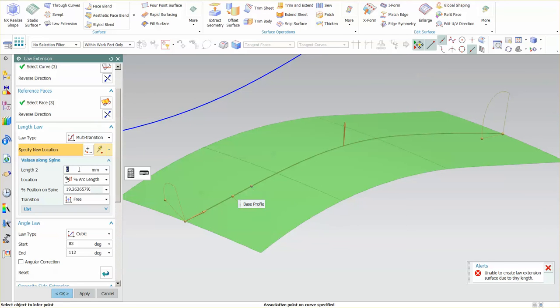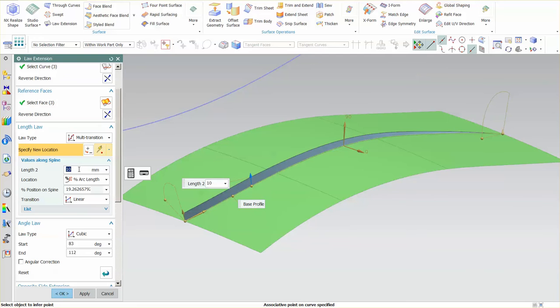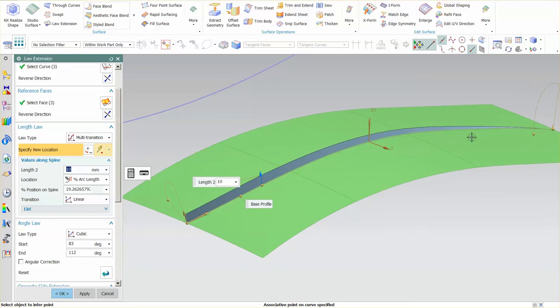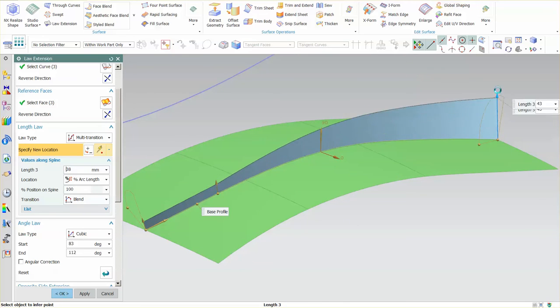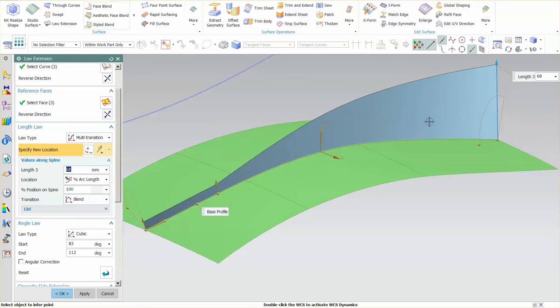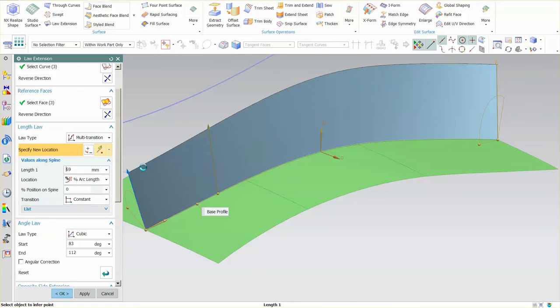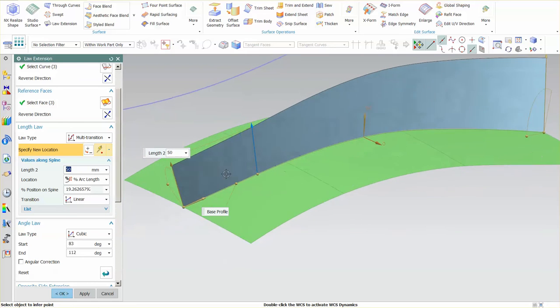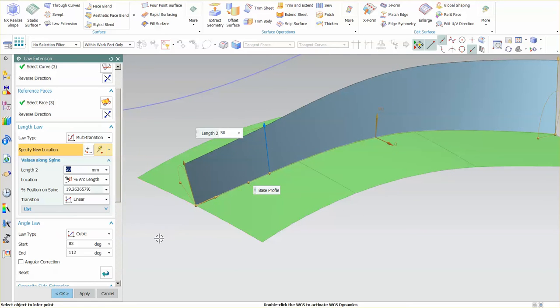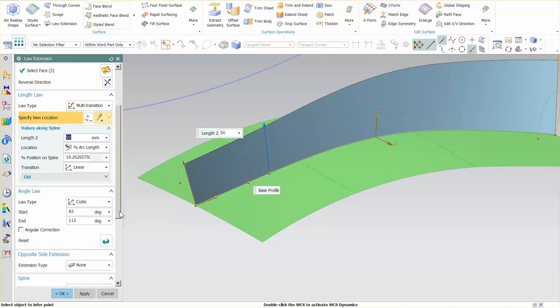So if I come over here and specify 10, you'll note that I'm coming from 0 to 10. So if I go to this end and I pick this and I transition up, I'm going to 10 millimeters right here. And at this end, I'm going to go up higher. And at this midpoint, I'm going to reduce it. These are currently locked. Let me add another point in.